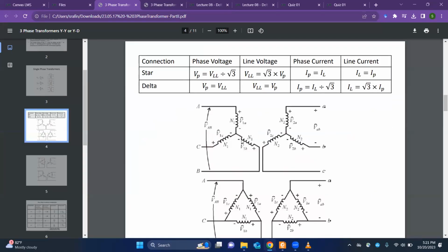All you have to do is take a note of those values, like current value and voltage value. We don't need power factor or the power for this case. Take a note of those measurements and calculate based on these formulas. In case of Y to Y, in one case I have measured phase voltage on the primary side and line to line voltage on the secondary side. So that's why the values were a bit different.